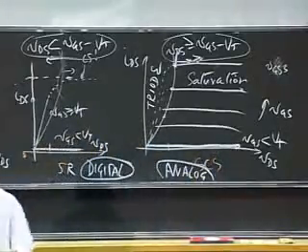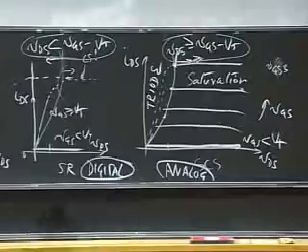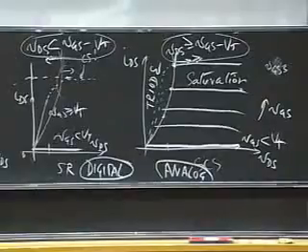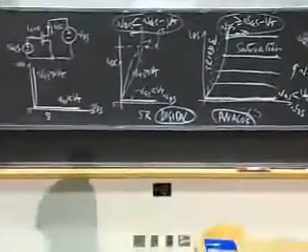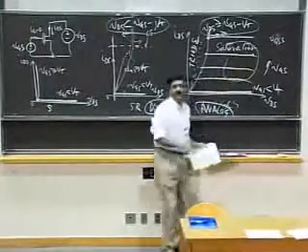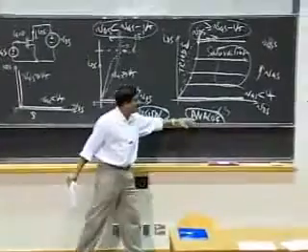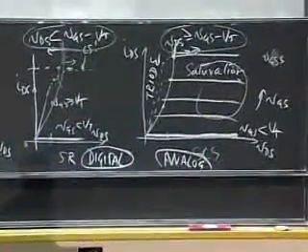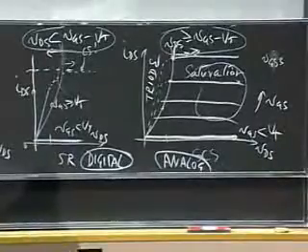We are going to constrain ourselves to play in only this region of the playground where VDS is quite large. Why? Because I'm asking you to. Let's play in that part of the playground and keep your VDS high, so the MOSFET is going to be operating somewhere in here. So we can apply just the SCS model, just the current source behavior in that region. There's another important reason which I'll get to in a second.